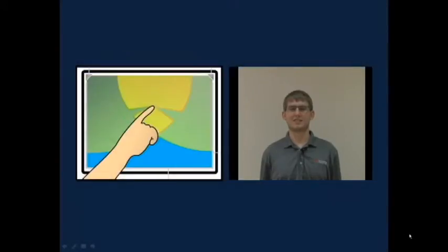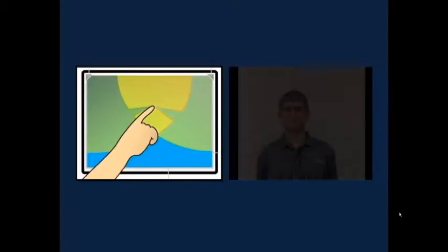The next section is touchscreen technology. We decided to use optical touchscreen technology. This uses the cameras to create an optical field that the user can then break with his finger, and that will create a shadow. The shadow is then caught on the cameras and that video feed is sent to the microcontroller. The microcontroller then processes the video feed and turns it into data we can use.